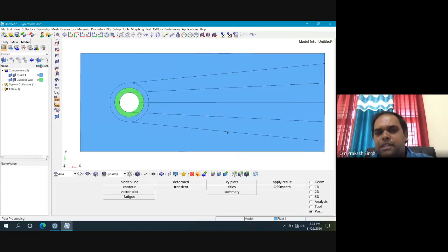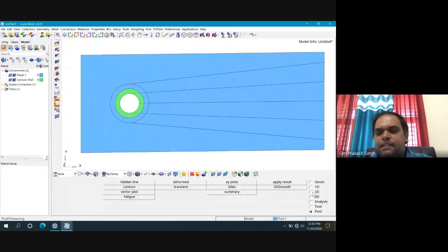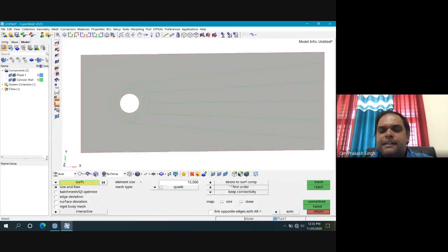Now, one mistake I have seen many students make in modeling such kinds of problems is they take a simple, arbitrary mesh size. You can have a quad, tria, or mixed. Mixed is generally preferred when the geometry is complex, so it will capture the geometry in a better way. But it doesn't matter as long as you maintain the proper quality of the mesh.